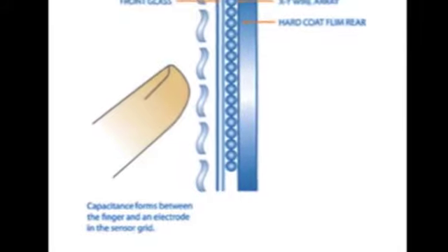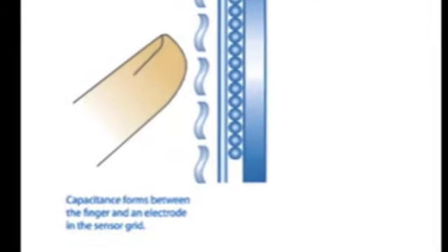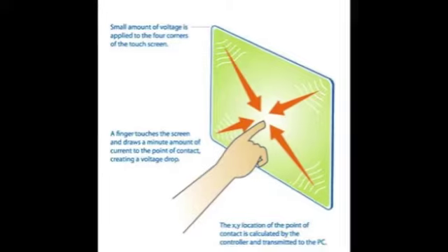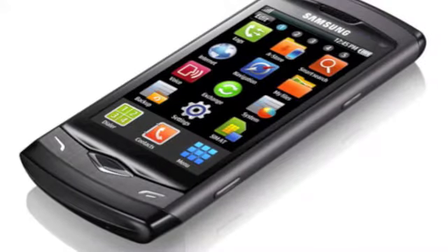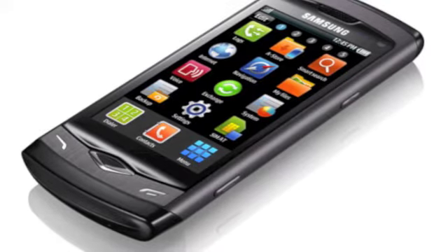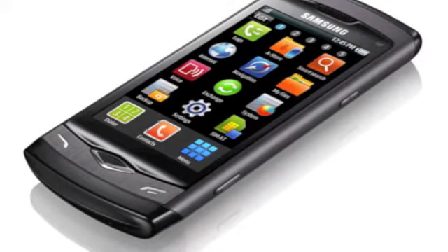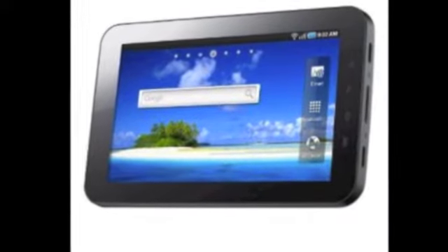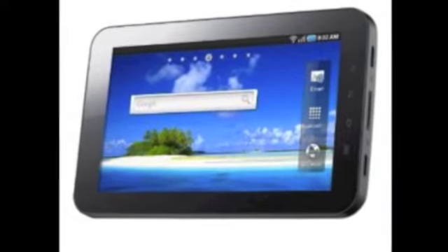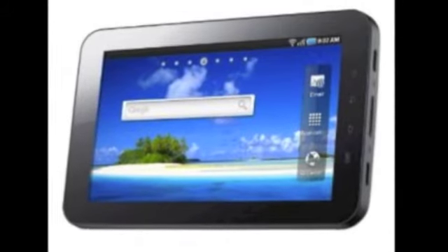Capacitive touchscreens use the capacitance of the user's finger to disrupt the current along the display, or the projected field in the case of projected capacitive touchscreens. Capacitive touchscreens were the first type of touchscreen ever used, and the newer projective capacitive technology is currently leading the way for touchscreen phones, tablets, and similar devices. While the sensitivity of the projective capacitive touchscreens can be enough that a glove finger can work, it would not work with a typical stylus.